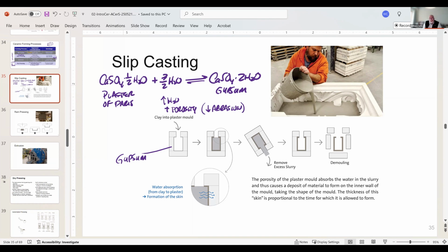If you make gypsum molds, you dry them without heat, because this calcium sulfate goes to what's called anhydrite, CaSO4 plus 2H2O that comes off as gas at about 96 degrees C. And then your molds crack. They don't work as molds anymore, and you destroy your molds. It's a typical undergraduate thing. They get a new mold in and put it in the dryer, and then the mold is destroyed.